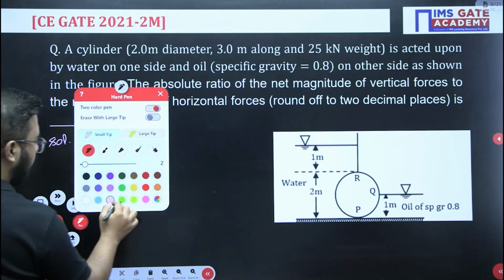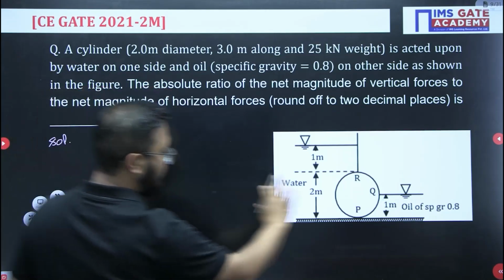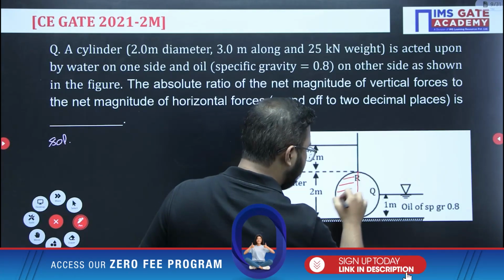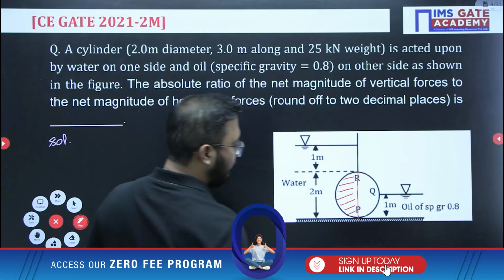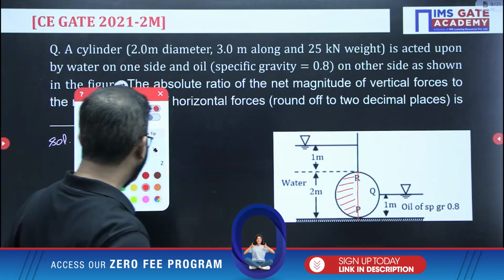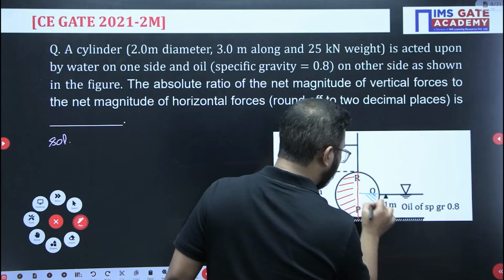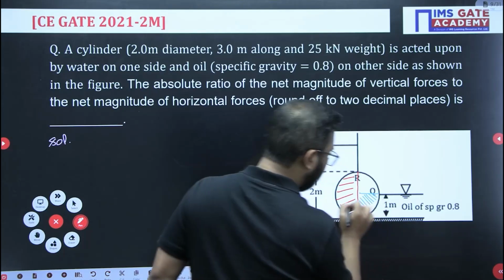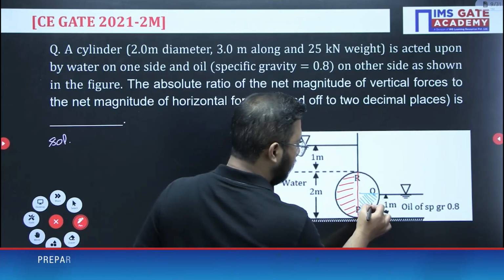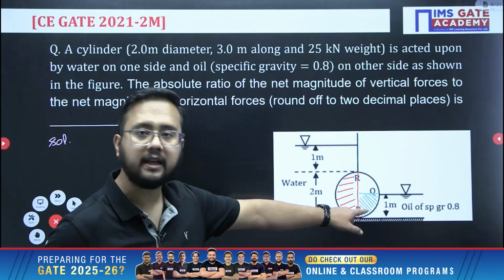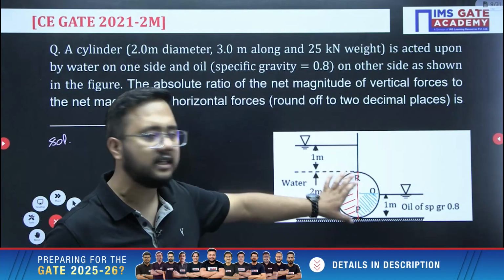So first of all, you need to understand the water is still here. Till this point, this is the curved surface we will be considering, this area for the water for calculation of the vertical force, and for oil this area we will be considering. Okay, so for oil this particular area we will be considering, and for this water this area we will be considering.